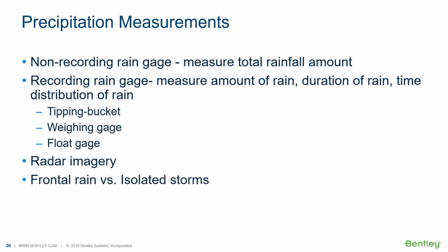You've got to be careful what kind of rainfall event you're dealing with, though, because when you try to calibrate the model, you'd like the rainfall over a given catchment or subcatchment to be fairly uniform. And that usually happens when you have these big frontal rains coming through, not these isolated thunderstorms. I'm sure you've been out sometimes where you'll be driving through a terrible torrential downpour, and then a mile later, the sun is shining and the pavement's dry.